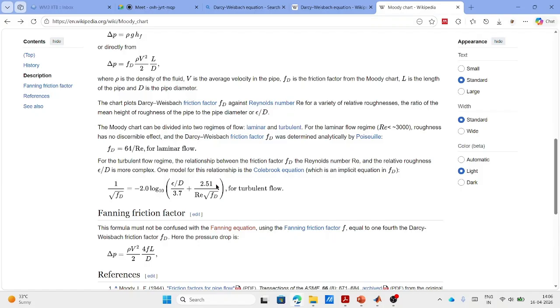So if I want to find, let's say for some flow condition, I know the Reynolds number, I can solve this non-linear equation. Right now you can see this is actually a non-linear equation. Why is it non-linear? Because you have this logarithmic term, your friction factor to the power half, right? In both cases, so this becomes a non-linear implicit equation, right? Because you have to solve the equation such that both sides become equal. So basically, you are optimizing the problem where f(x) equals 0 occurs, right?